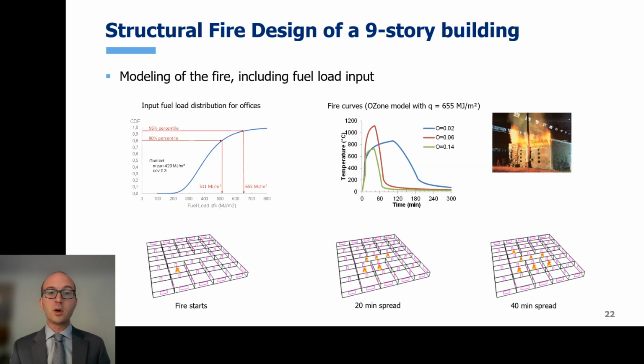If there is more ventilation, the fire might be shorter but more intense, as opposed to if there is a shortage of oxygen. So we ran sensitivity analysis, and eventually we defined two fires for each scenario for different sets of parameters. We also have an assumption, when we have fire spread in the floor plan, of a delay between ignitions in adjacent compartments.